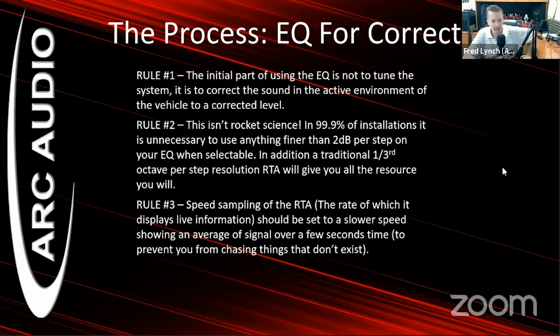I literally had a guy who said he had his RTA set up at the fastest speed because it made it easier and more enjoyable to tune with the lines dancing much faster. Real simple, slow it down. It'll take an average over a few seconds time, depending on your sample rate, and it'll prevent you from chasing things that just simply don't exist.